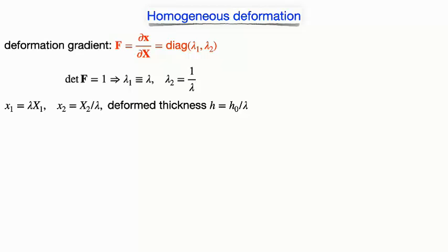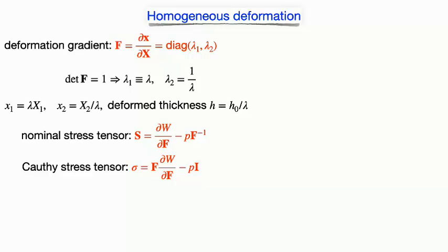It's very simple algebra, actually. And this is the definition of the nominal stress and the Cauchy stress. You can derive this, and then this is the force equilibrium. Actually, for homogeneous deformation, because the stress tensor is constant, this is satisfied automatically. You don't need to solve this.